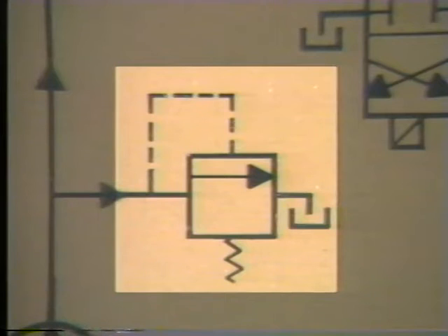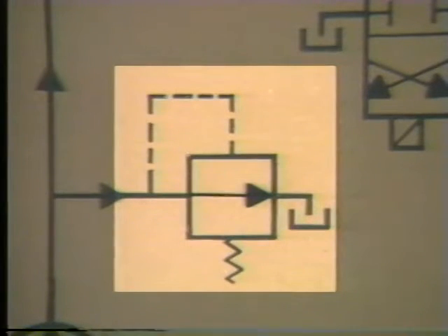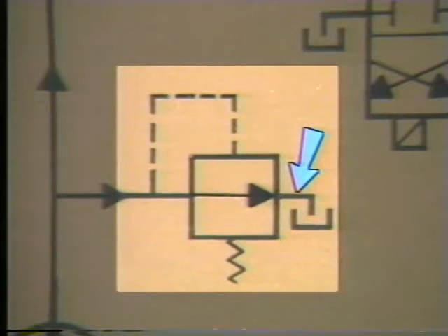It puts the pressure developed at the discharge of the pump on top of a spring-loaded valving mechanism. When pump pressure exceeds a predetermined value, the valving mechanism, such as a poppet or spool, is pushed down, opening up a passageway inside the valve. Some of the hydraulic fluid then flows through the valve and back to the reservoir, thereby reducing system pressure. This symbol, attached to the valve, indicates a return line to the reservoir.